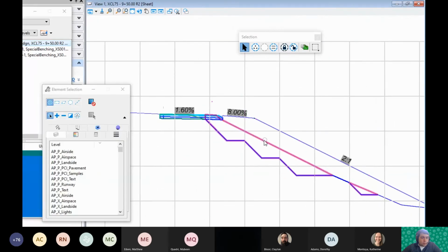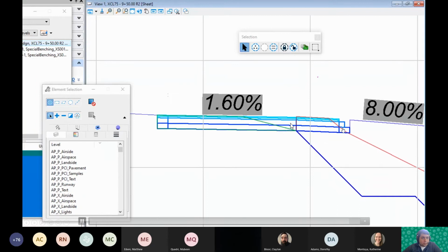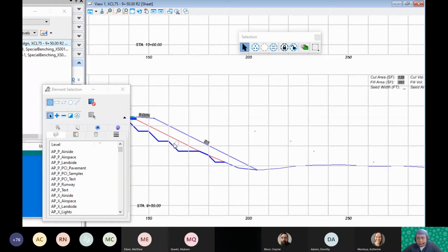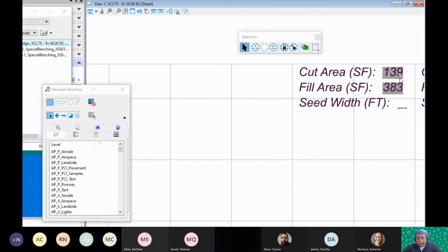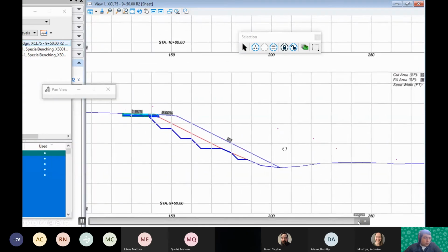So there's some other things to be looked at still, but in that case, that's the earthworks. All we're doing is creating that cut quantity in a new surface, and then you normally would have generated your cut fill quantities anyway. So it's just adding those 2 extra steps when you go to do your earthwork quantities. So hopefully that's pretty cool to people.